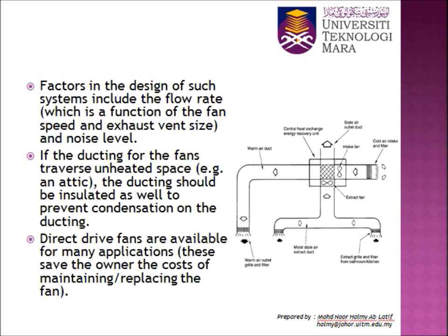Next, factors in the design of such system include the flow rate, which is a function of the fan speed and exhaust vent size, and also noise level. Okay. If the ducting for the fans traverse unheated space, example an attic, the ducting should be insulated as well to prevent condensation of the ducting. Direct drive fans are available for many applications. This saves the owner the cost of maintaining and replacing the fan.